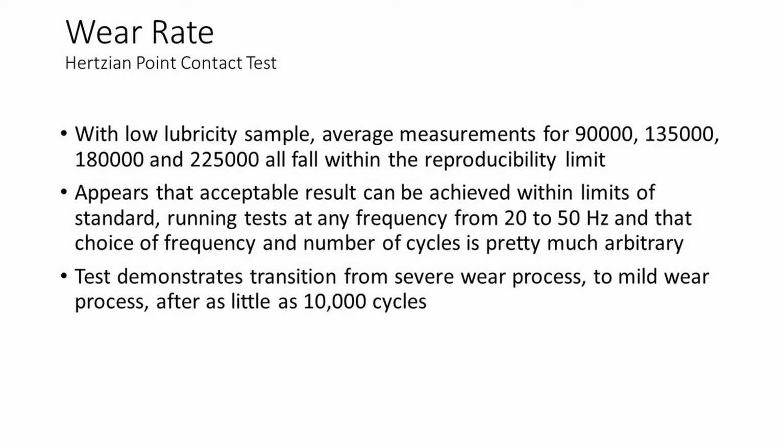It would appear that an acceptable result can be achieved within the limits of the standard, running the tests at any frequency from 20 to 50 Hz, and that the choice of frequency and number of cycles is pretty much arbitrary. However, in practice what it demonstrates is a transition from a severe wear process to a mild wear process after perhaps as little as 10,000 cycles, after which the test continues to run on what is an already heavily worn or deformed surface.